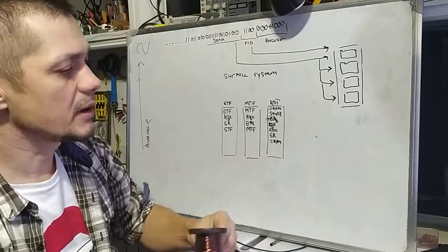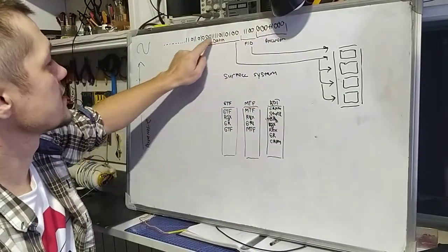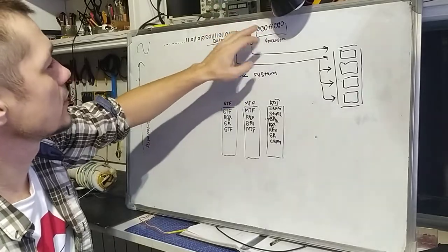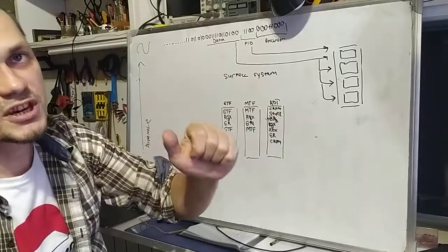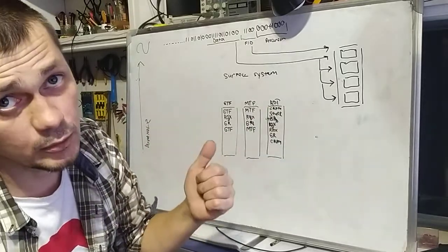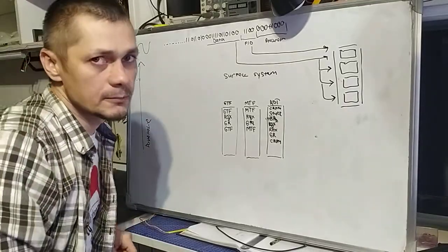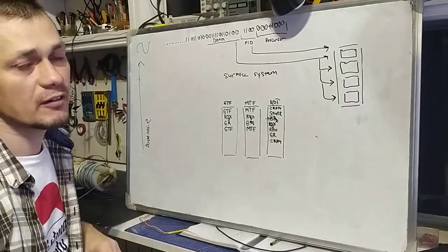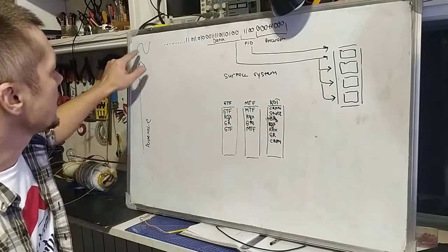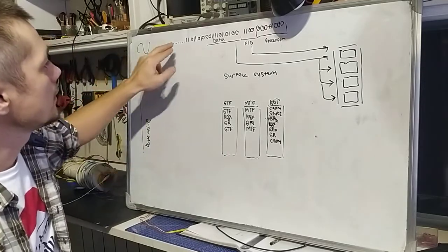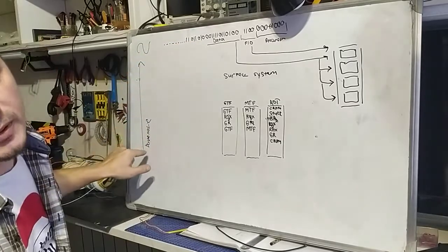This line is basically presented as digital words coming in different sequences like 0, 0, 1, and so on. It comes continuously when you're drilling and when you have the signal from the MWD tool. So how it basically works: when you bring the pumps on, depending on what kind of tool you have, the tool will start to rotate the modulator and create pulses. These pulses code some digits which were coded before in the tool's memory.